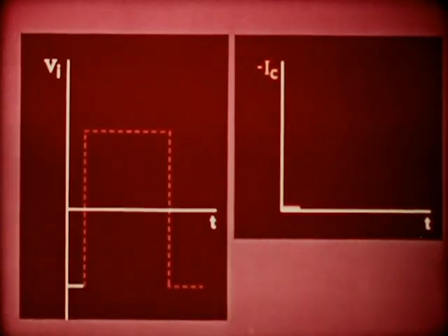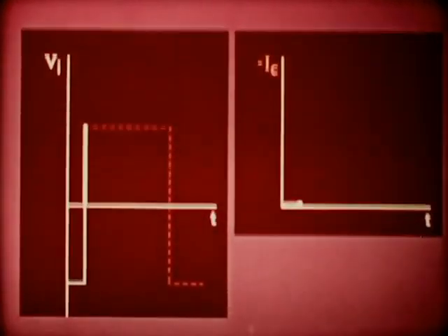What happens then when this high stepped voltage pulse is applied? The application of the pulse sets up an input current. But the electrons entering the base do not disappear due to recombination, because the concentration of holes in the base is still very low.